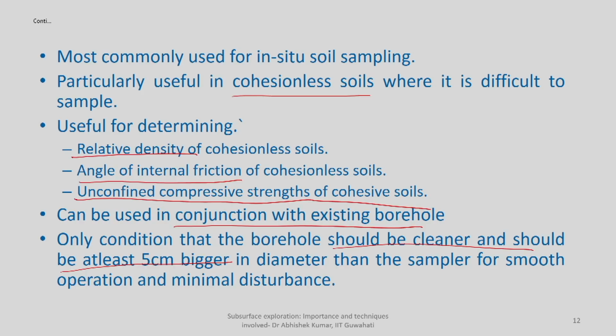If the borehole is of the same diameter as the sampler, first of all there will be a chance of wear and tear. Second, when you are trying to measure the in situ strength in terms of resistance offered by the soil, some component based on the roughness of the borehole wall in contact with the sampler will give you additional resistance. So you will end up overestimating the soil resistance.